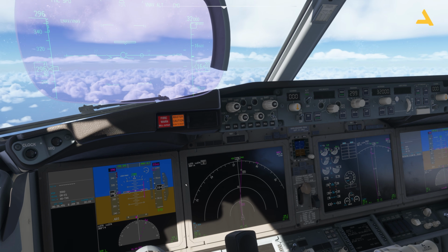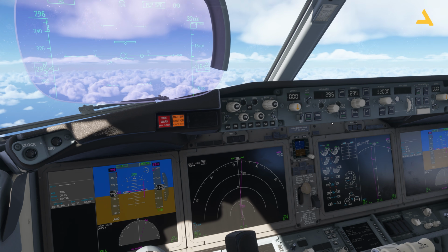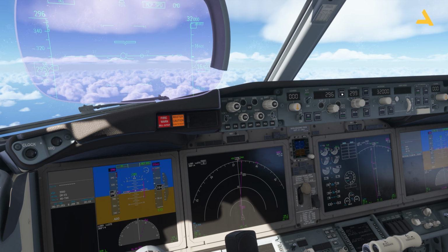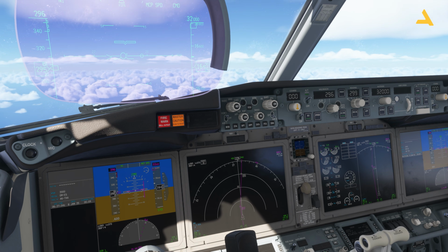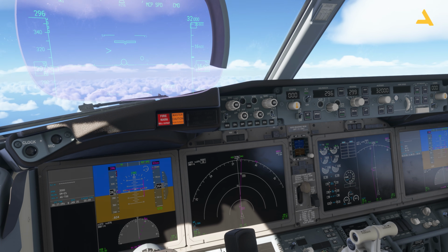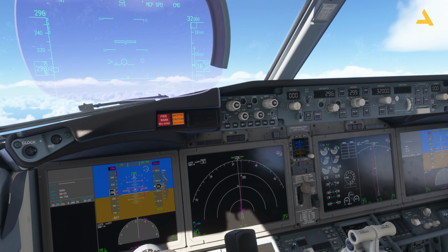No, it will not. And for this, again, if you press this button, the climb should start, but if it doesn't, then you can press the level change button. Then the climb will start, and then at any time, you can just go back to the VNAV mode. Let's see if it works. Yes, it takes some time. Now the climb has started.